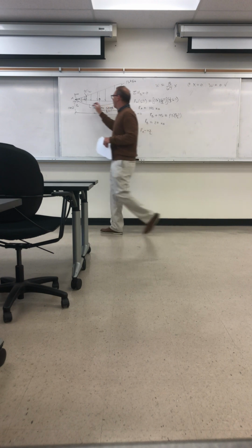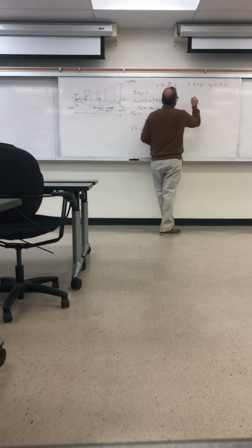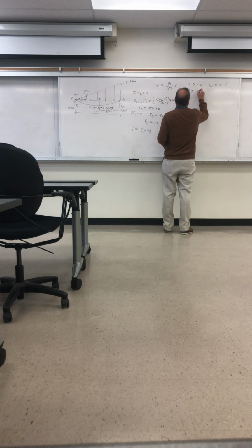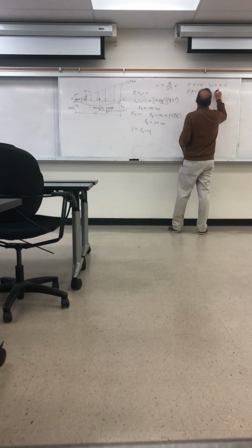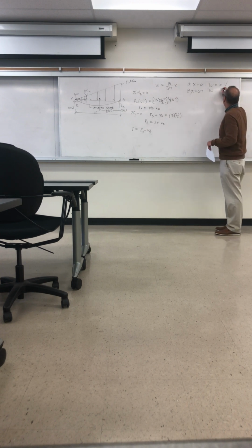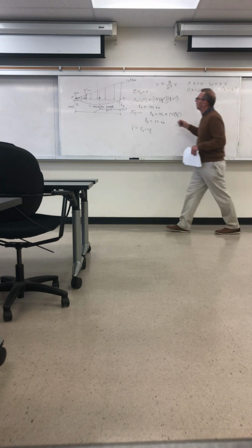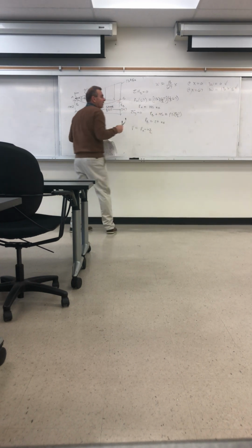That's correct. At this point, the intensity of the distributed load is 0. At x is 67, the distributed load, we put in 67 here, that cancels with that, and you get 13 kips. That's at the right. And then it's a linear variation.